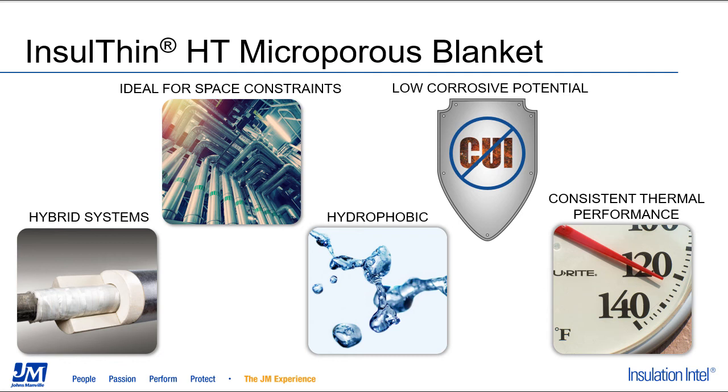It is also a hydrophobic insulation product, and a very important feature for the microporous thin blanket is that it also has a very consistent thermal performance, so no change in thermal conductivity with exposure to elevated temperatures, as you might see with some other products.